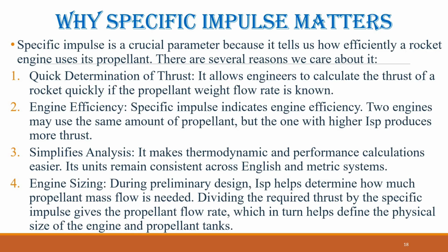In summary, specific impulse not only gives a quick way to estimate thrust, but also serves as a measure of engine efficiency, simplifies calculations, and guides engine design. A similar performance parameter used for turbine engines is called specific thrust, which characterizes their efficiency.